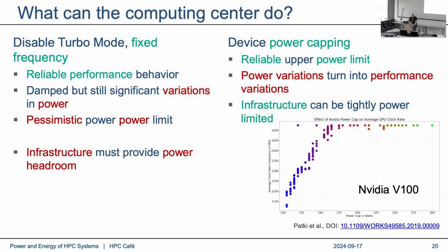No, it doesn't shut down. There's a feedback loop that makes sure that if you run hot code that would otherwise be close to the thermal design limit, it would run at a lower frequency. And cold code, which makes less use of the hot parts of the CPU, will run at higher clock speeds. So that's a dynamic thing that happens within the CPU, and it's very reliable. So the CPU does everything in its power to keep within this limit. It doesn't shut off anything. It doesn't stop your job. It just adjusts its clock frequency so that the power dissipation is never beyond the limit that you set.